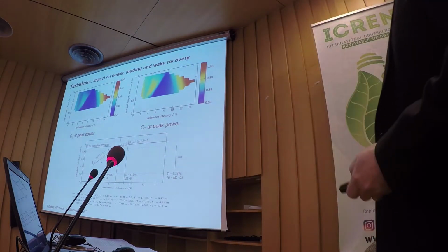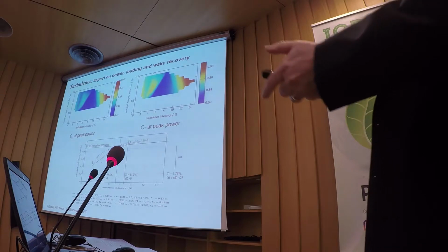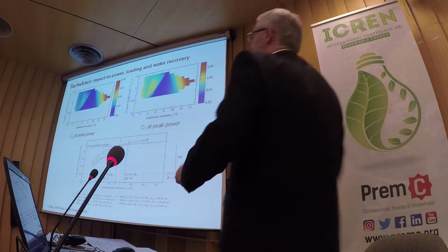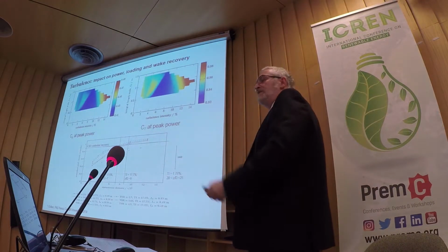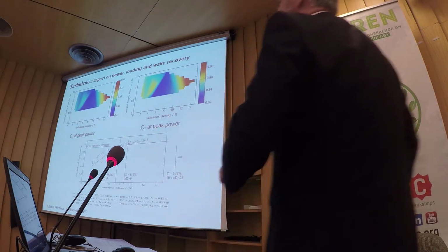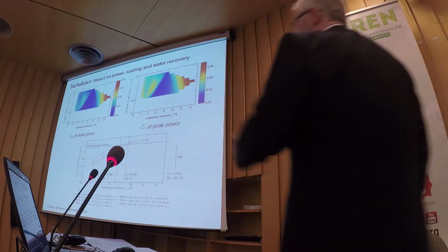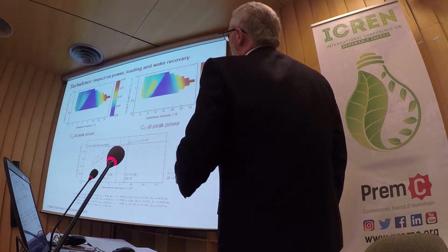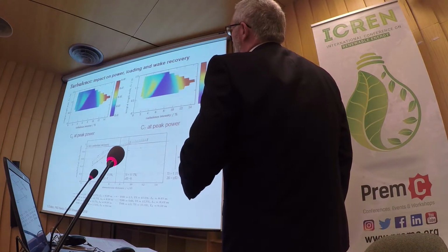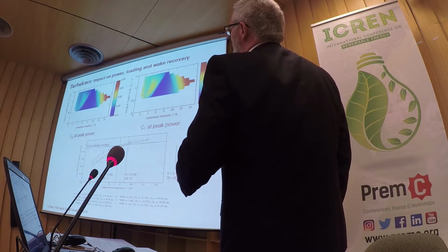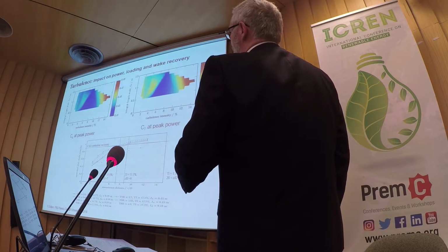So what does turbulence actually do for us? Well, the problem with turbulence is it can come with different length scales, so eddy sizes, but you've also got this thing called turbulence intensity, so the root mean square value over a mean velocity. And when you actually plot out the turbulence intensity over the length scale, you can see the various effects on it.